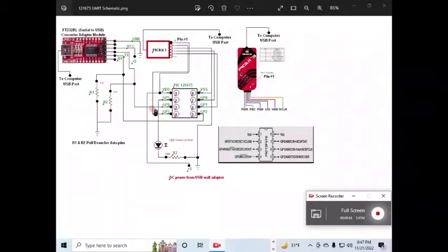Coming off the PIC, I just have an LED that flashes to let me know that the PIC is up and running. Then of course I have the TX data line connected to an FT232RL serial to USB converter adapter module, and that has a USB cable coming off it that goes to the USB port on my computer. The RX line I have connected, but it's not going to be used in this demonstration. I have two 1K pull down resistors, one on the RX line, one on the TX line.